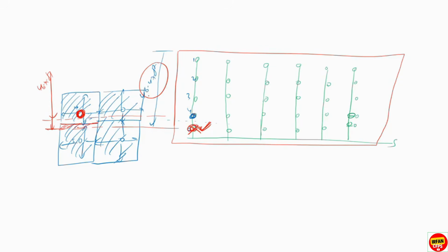If you consider the 5th sprinkler, then the length of the design area increases from 46.47 to somewhere around, for example, 56.5 feet. So this will be the revised length of the design area. 56.5 feet is the revised length.